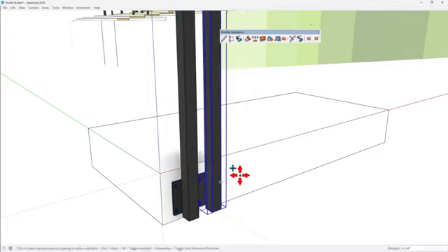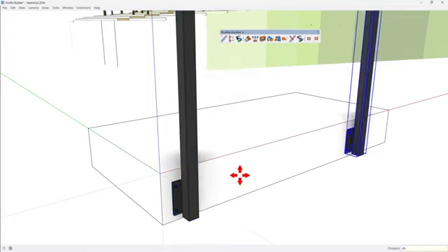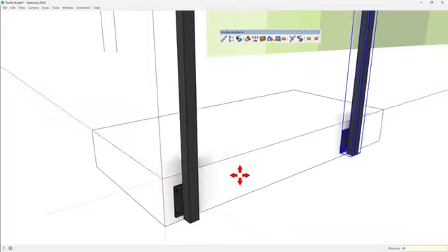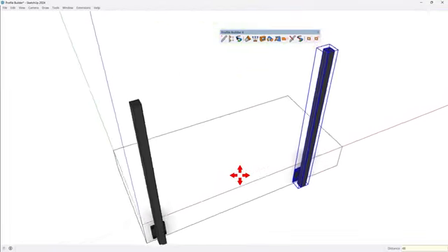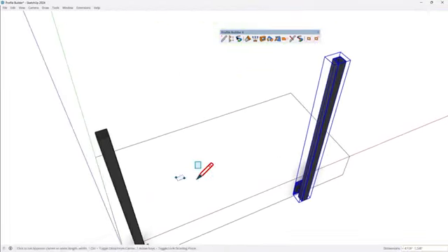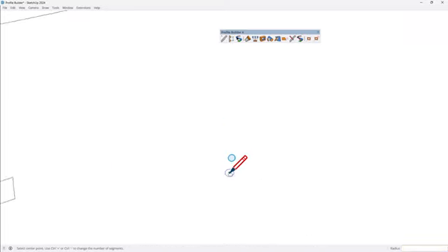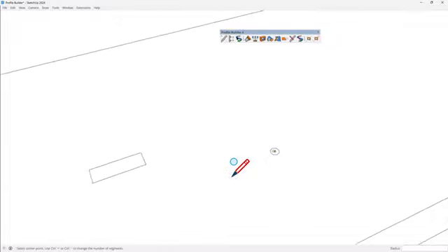So I'll click create. I'll move and copy this over 48 inches because that's my span that I can do. And then I need to create 2 profiles. One is going to be 4.5 by 1.5 inches. And the other is going to be a circle that is 0.125 and it is 8-sided, so 8S. The reason for the 8 sides, or creating an octagon, is when this is extruded, it still looks like a cylinder, which is going to keep the polygon count low.